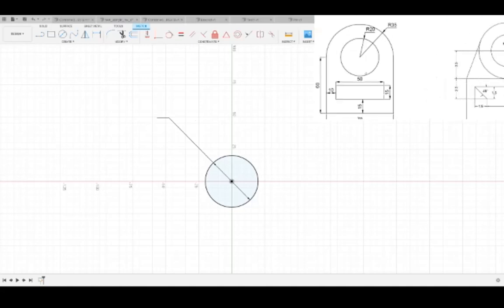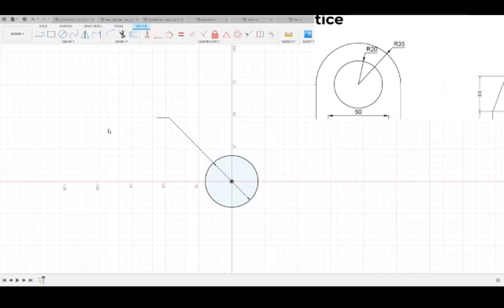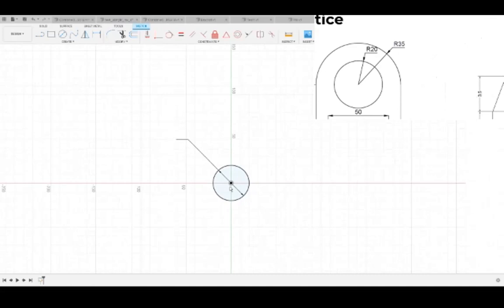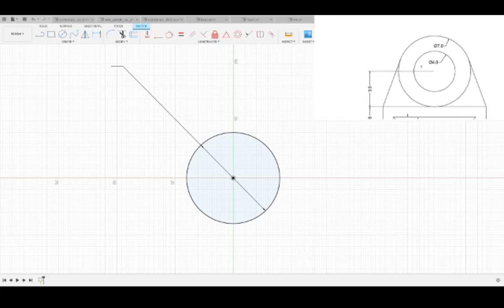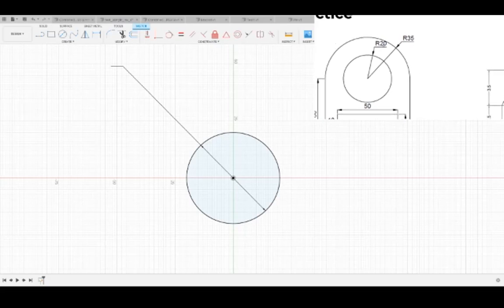So if we set this guy to, as seen in our little drawing up here, which, can I zoom in on this? How about that? It has a radius of 20 millimeters. Something to note here as well is that the leader on this dimension only goes from the center out. That means this is a radius dimension, not a diameter one, whereas the leader on this dimension in Fusion goes from end to end, which implies it's a diameter. Often if you don't see a diameter symbol, which you would see on, can I move this? Yeah, there you go. As seen here, this little guy is a diameter symbol for those who have not seen it. That is what differentiates the two, because often you may overlook it, and then you'll wonder why your circles are half as big or twice as big, depending on which way you're going.